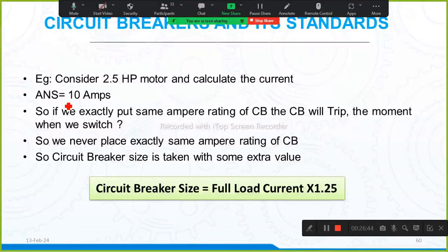Okay, you'll get fuses. Like for example, you see in your home grinder. In your grinder, at the bottom, you'll have a fuse, apart from the normal circuit. Because the manufacturer doesn't have a circuit breaker for 12 amps MCB or 13 amps MCB, it's not there. So you need to put a fuse. Like you'll put a 14 amps or 12 amps fuse. Then if it is more than 12 amps, it will trip off.